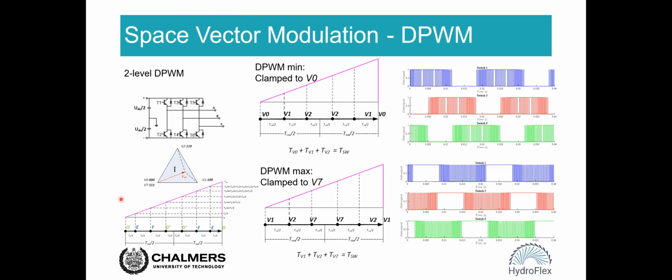And if we look at this sawtooth waveform, which we use to determine the switching signal inside the converter, we can see we will have 7 segments here. Basically, this D prime is the same vector as this VD. So the general idea of discontinuous PWM is to remove these 2 D prime vectors here. So we just use the voltage D, the voltage E and the voltage F, but we can synthesize the reference voltage here.